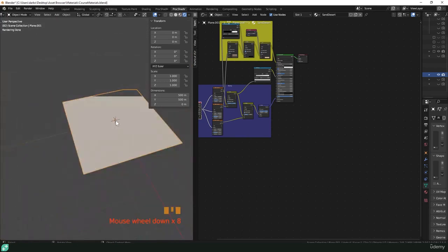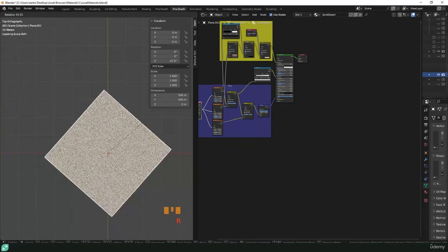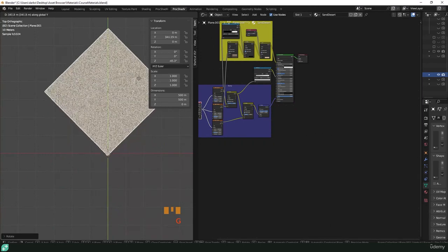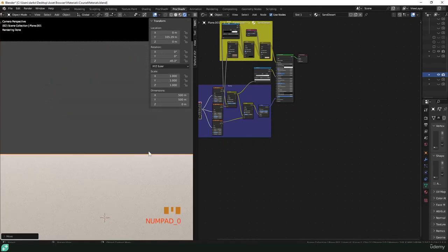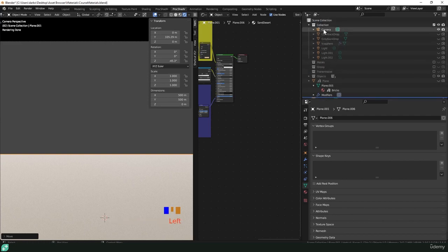Let's just go into our top view. We're going to rotate this around about 45 degrees, and we're just going to move it up in Y, so when our camera looks at our plane, now we're seeing a lot more of that. Now at the moment our plane is 500 by 500 meters, which means from corner to corner we're getting quite a big distance. At this very large distance the camera may start clipping, so let's just check.